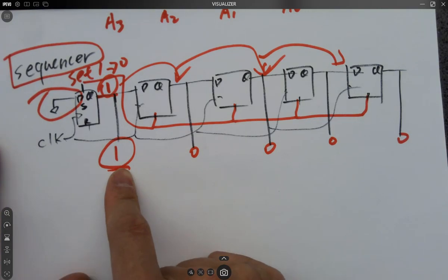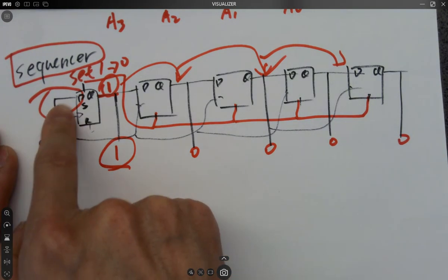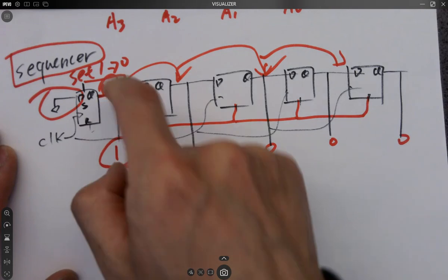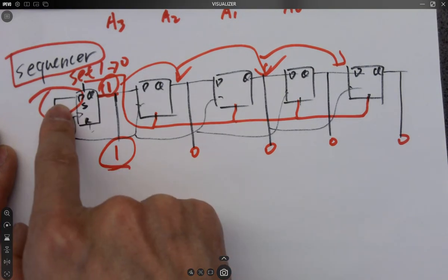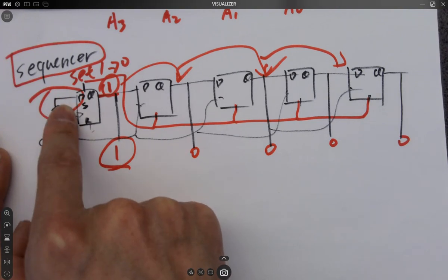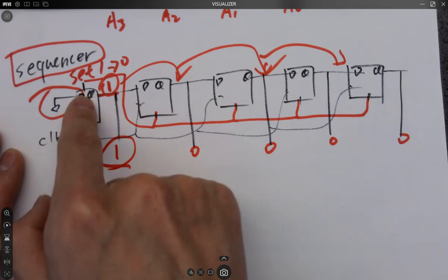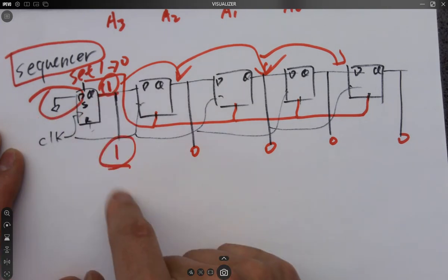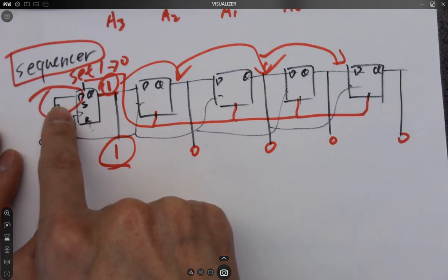Very last question, I promise you guys. Why is this 0 not being sent or latched to the first one? Nobody here is switching it back and forth, right? It's permanently shorted to ground. So why is this not being latched to ground? It's a D flip-flop sending D to Q. Why is it not being reset or latched to ground?